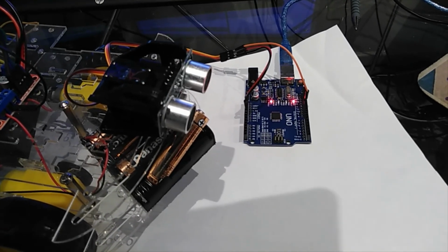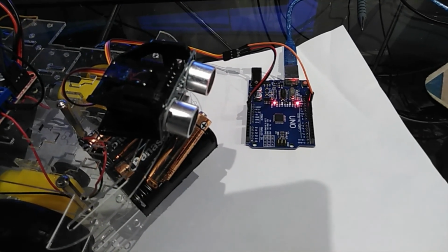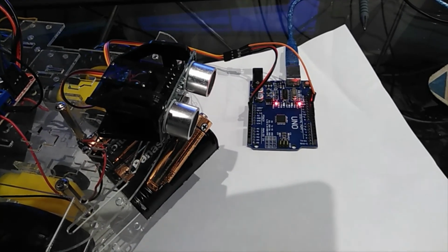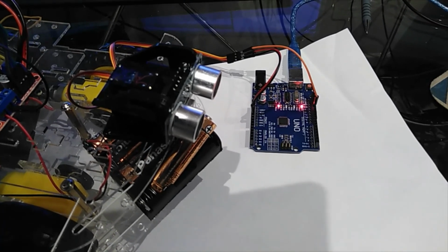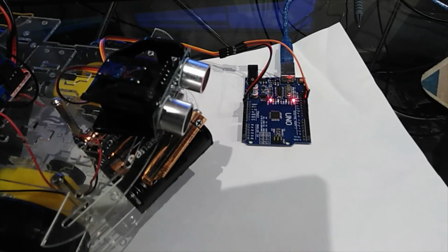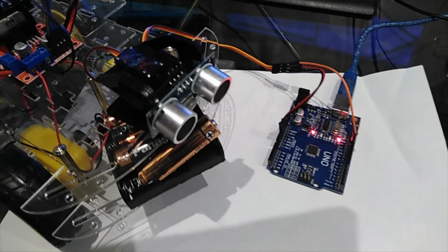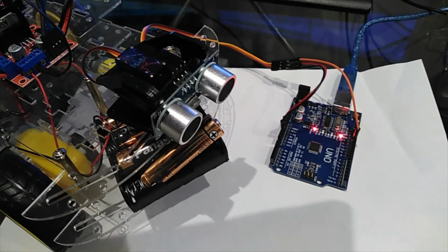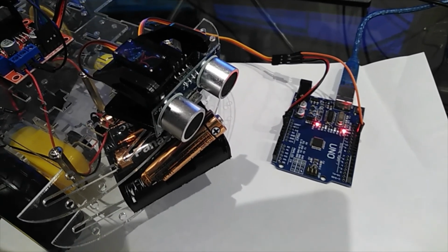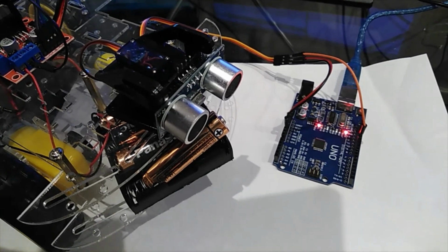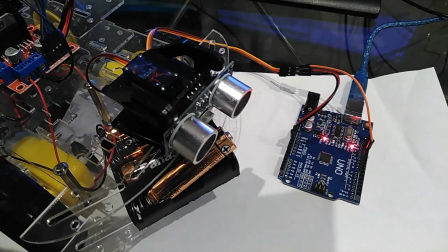It's very easy with these servos to attach the units to it, but actually to have attached it while the servo is at position 0 or position 60, so that when you run your code, you suddenly find that your ultrasonic sensor is pointing off in an odd direction. So I've included the servo setter code, which once you've run it and the code has ended, that is the position to screw the bracket together onto the top of your servo.